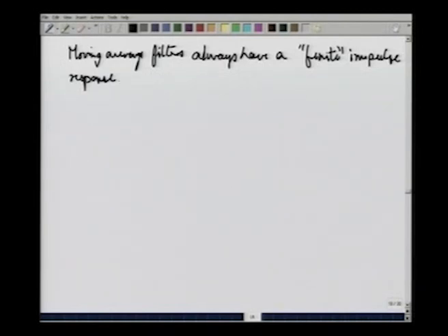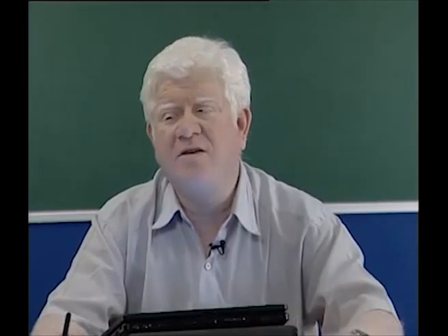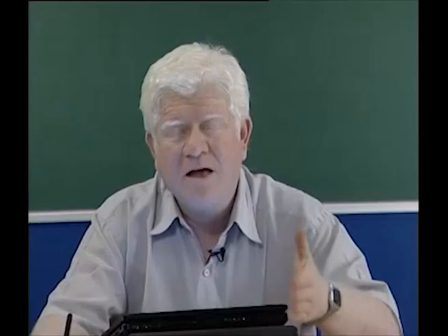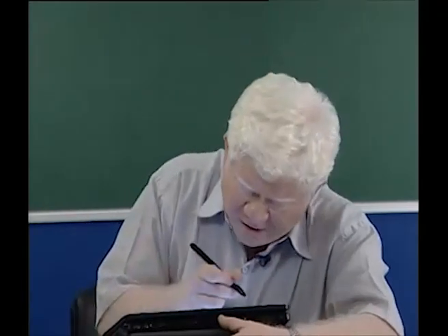That is because the moving average filter simply sums up certain previous values of x n with appropriate scales. That is all it does, and the number of previous values of x n that are added is simply capital M. That many previous values of x n are being added together. That is why the impulse response of this is very, very easily calculated.